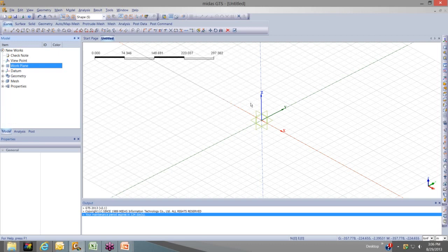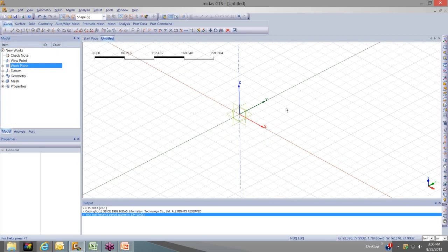And then let's do our geometry. In order to create geometry in GTS, there are several different options available to you. So here you have the different options for curves, rectangles, arcs, etc. I won't go into too much detail about the geometry yet, but for now let's just start with our top section, which is the rectangle, which will represent our solid for our soil.